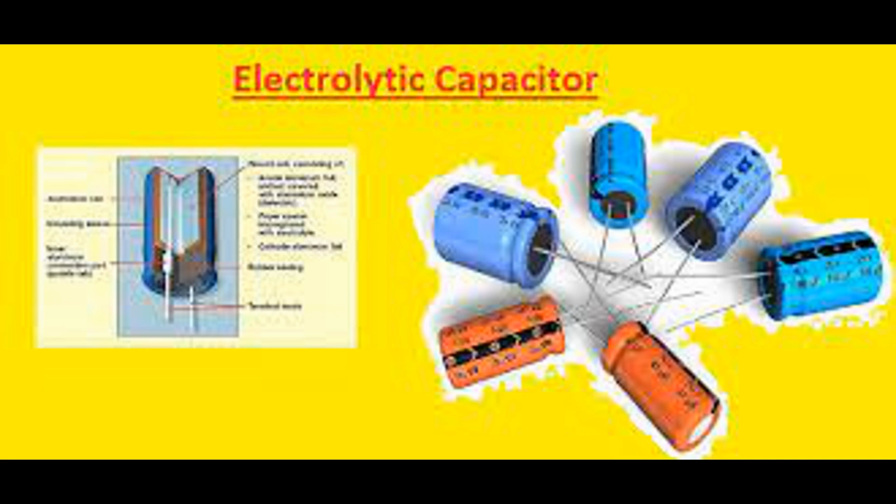Coupling capacitors pass audio signals from one stage of the amplifier to the next while preventing DC bias from affecting subsequent stages. Example. In a multi-stage audio amplifier, coupling capacitors ensure that each stage receives the correct audio signal without interference from DC voltages. Signal processing.